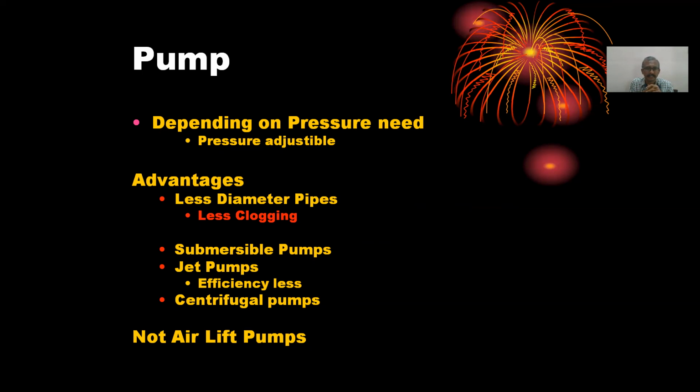And the advantages, as I said, in relation to the overhead tank: with the pump, the design diameter of the pipes will be less, and you will be able to get more pressure. So the clogging problem will also be very, very less.